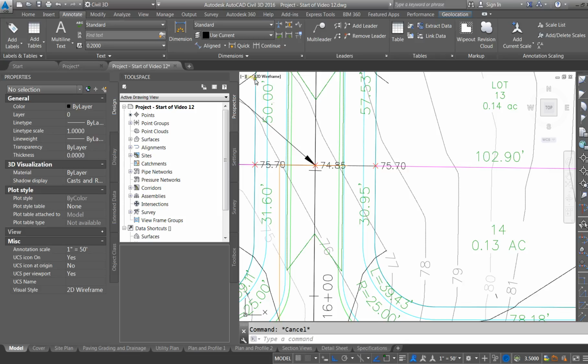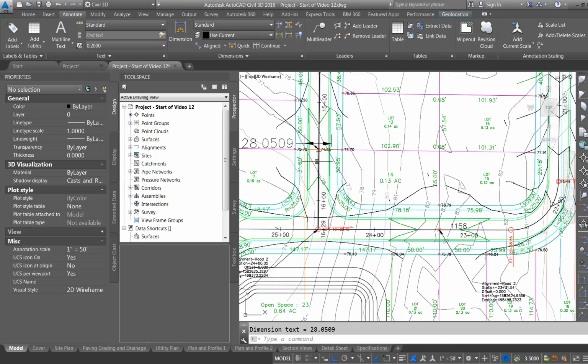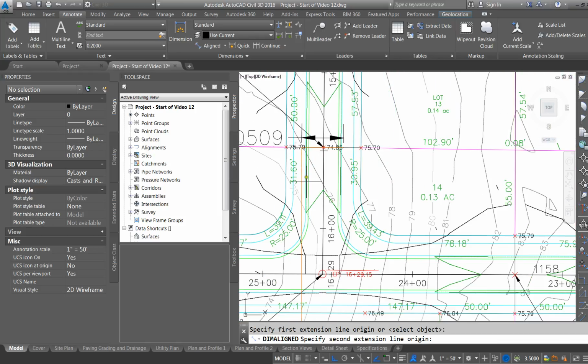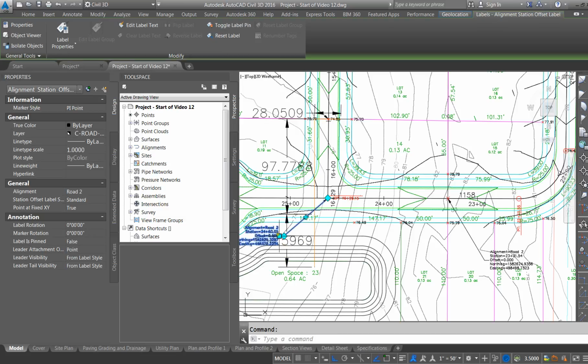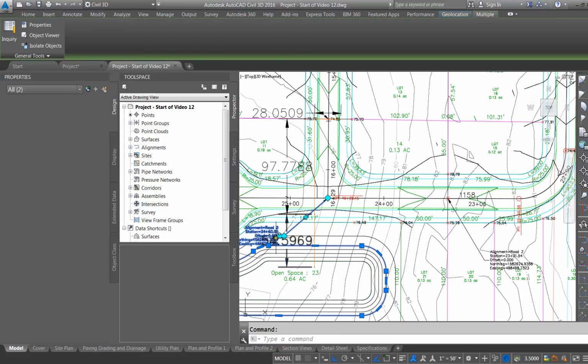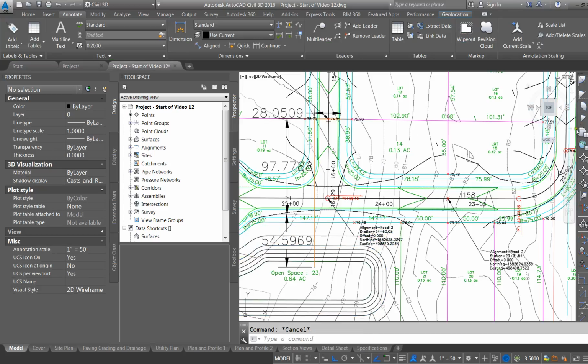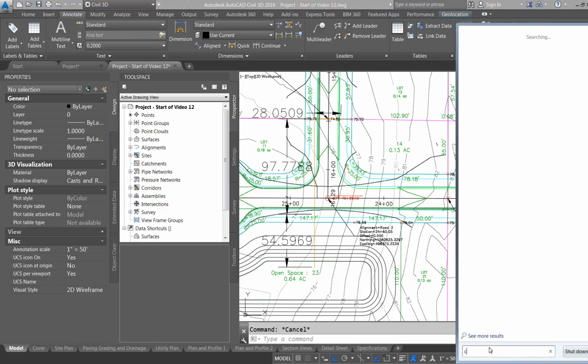All right. So I'm going to figure out what the distance is from this endpoint to this endpoint, and these are when we start to do the calculations, they will be modified. But the typical slope we have on our pipe here in Florida, because we're so flat, is about 0.25%. So I'm going to get my calculator open. So let me do that. Calculator.